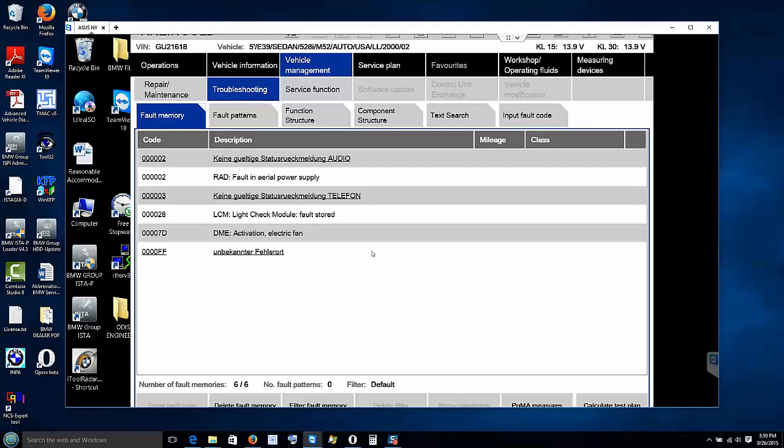Okay. Well, the FRM needs to be reset. It's a fault counter that will reach a maximum. I don't know if it's 50 on the E39, and each time you turn the key on and it still detects the fault, it increments the count by 1. So BMW allows it to max out at 50. What you can do is reset it using Toolset 32, or we can use ISTA-D to reset it. We can try it here if you want. Yeah, let's try that.